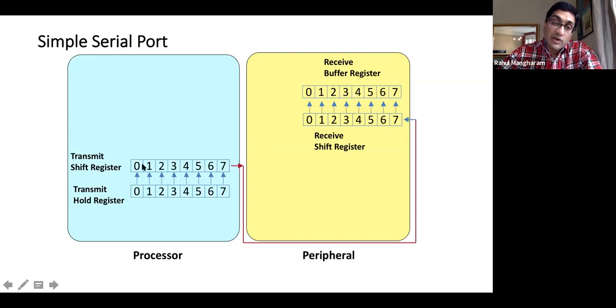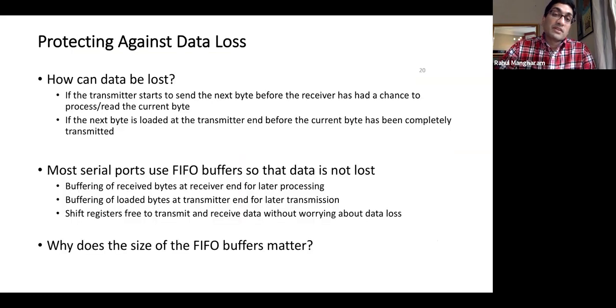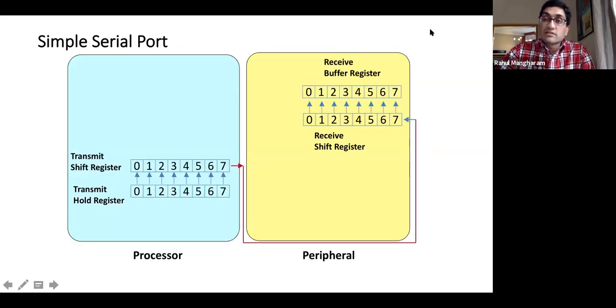So it basically requires 8 clock cycles, or 8 clock ticks on the sender, to send the whole byte across to the receiver, right? If we had a parallel line, it would just require one clock tick to send all 8 bits across over here, right? So does that answer that question regarding serial versus parallel? Or you had another related question to that?